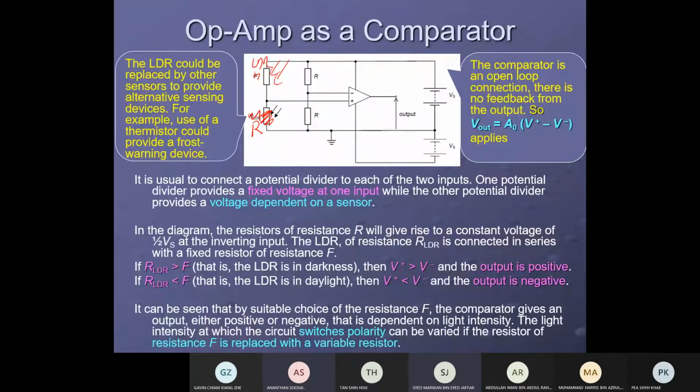What type of problem are you going to face? Will the light light up in the morning or in the night? Because the LDR is on top, it will end up lighting up in the morning. So a small change in the location of the LDR changes the result.